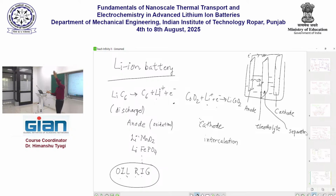This separator is a material which has the capability of letting lithium ions pass through it, but the electrons don't pass. The electrons only have a choice of passing externally, and therefore the separator plays a very important role of not allowing a short to happen between the anode and the cathode. So roughly speaking, this is what a lithium ion cell will look like.